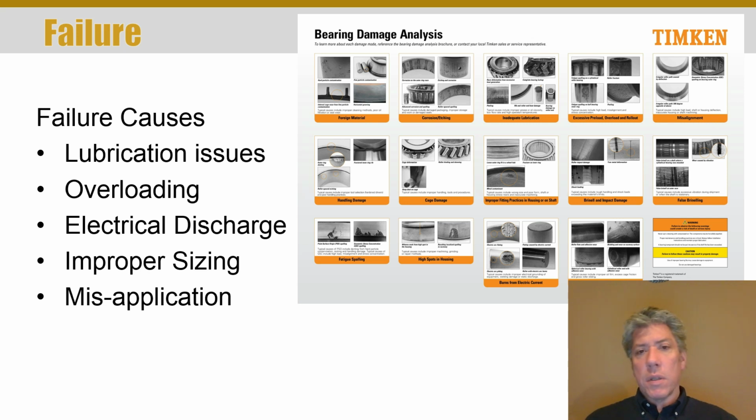That's because the tolerances in bearings are usually about an order of magnitude higher than typical machining. Usually you've got tolerances on the order of 1/10,000th of an inch, or 0.0001. So it's the 10,000ths place after the decimal point, that's where the tolerances for these bearings typically begin.